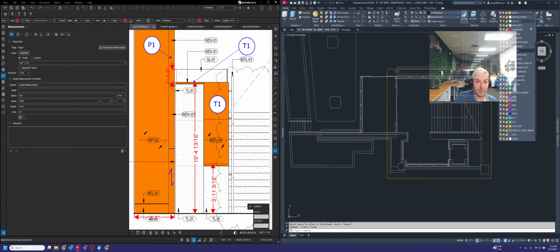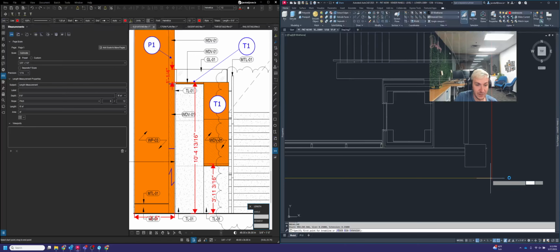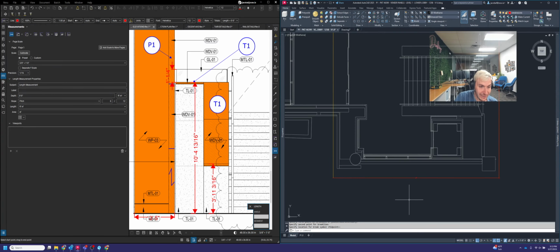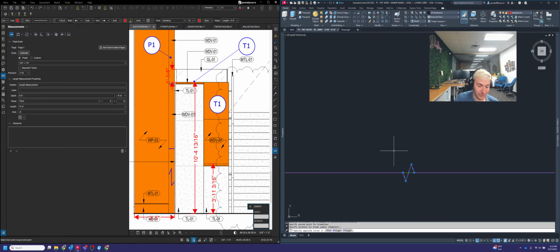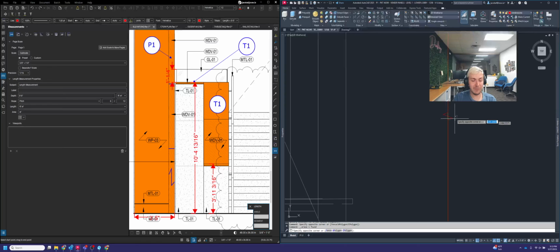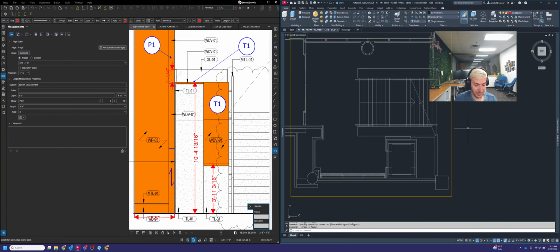Then from there, I'm going to throw in break lines. So let's throw in some break lines around the room, drawing over top of that rectangle we drew. If you're drawing in break lines and you notice, hey, my break line looks really small, it looks too dinky, what I'm going to do is go in here, go to break line, and at the very bottom you can see there are two options for size and extension.